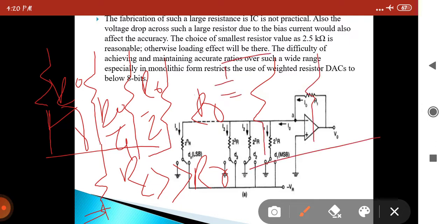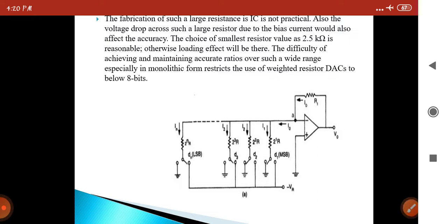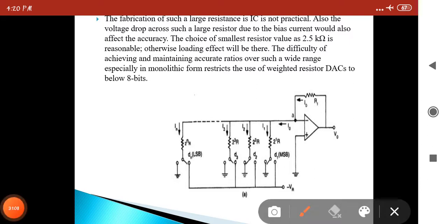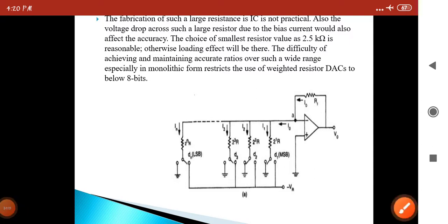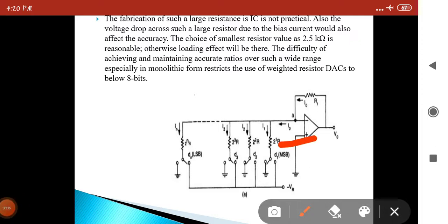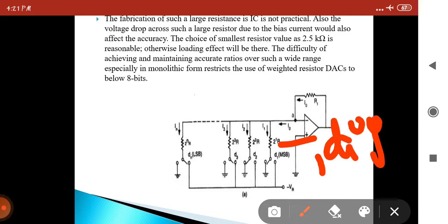R naught by 8, R naught by 4 can be written in the resistive ladder network. To summarize, the resistive divider is used for changing the digital voltage into the equivalent analog voltage. There must be one input resistor for each digital bit.